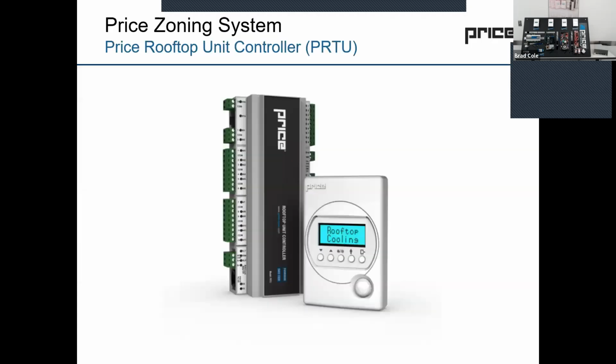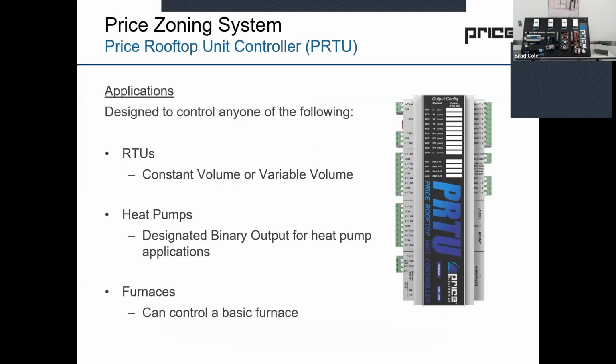All right, we're getting into the zone controllers now. So let's look at the PRTU, or the rooftop controller. Start from the top down. Essentially, this is a rooftop controller that we developed in about 2012. It's designed to control any one of the following: constant volume or variable volume type unit. It can also control heat pumps, which were commonly used in the TD Ameritrades that we went into, and then just basic furnace control. But really, we're looking at constant volume or variable volume type rooftops, anywhere from, say, 2 to 30 tons.